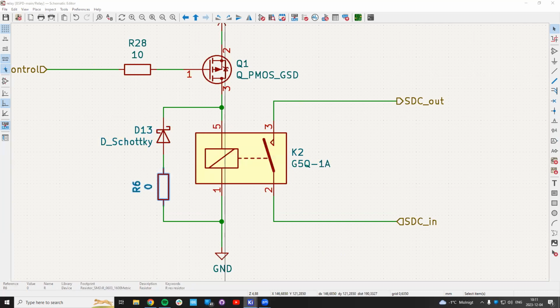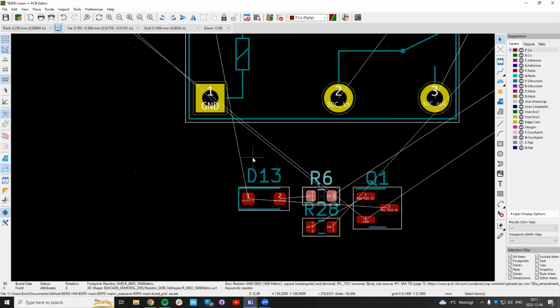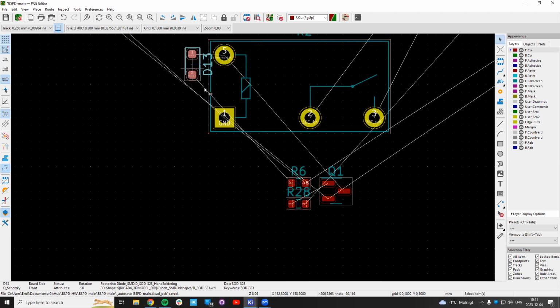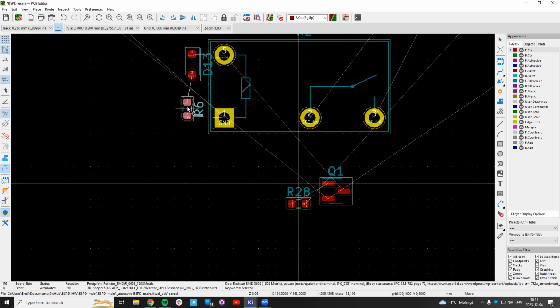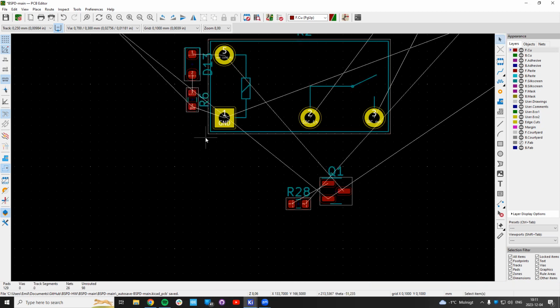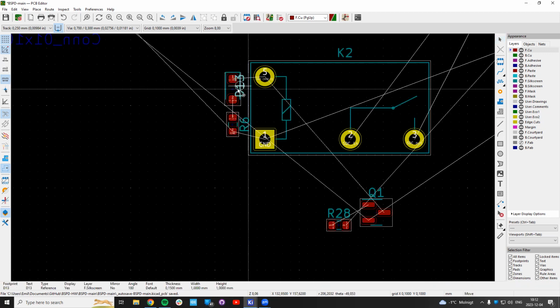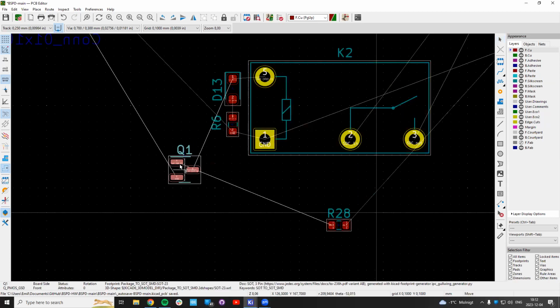So these two are going between these 2 points, and we want to keep them close for that reason. So we'll do this, and you can kind of see it here in the very descriptive silk screen that we want to keep this feedback path here close. Here, this also indicates that it's a load. And here is the switching. We have this transistor.